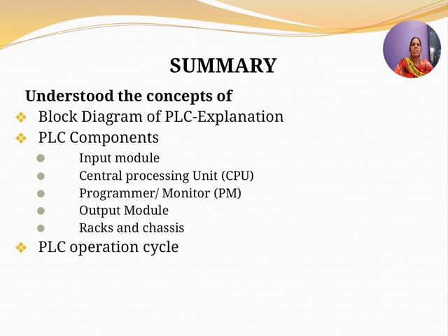So with this, we have discussed the block diagram of PLC in detail, the various components of the PLC, how they are designed, that is the input module, the output module, the central processing unit, the programmer or the monitor, and the rack and the chassis, the role of the rack and the chassis in PLCs. And we have also studied the operation cycle of the PLC, that is the PLC scanning method.